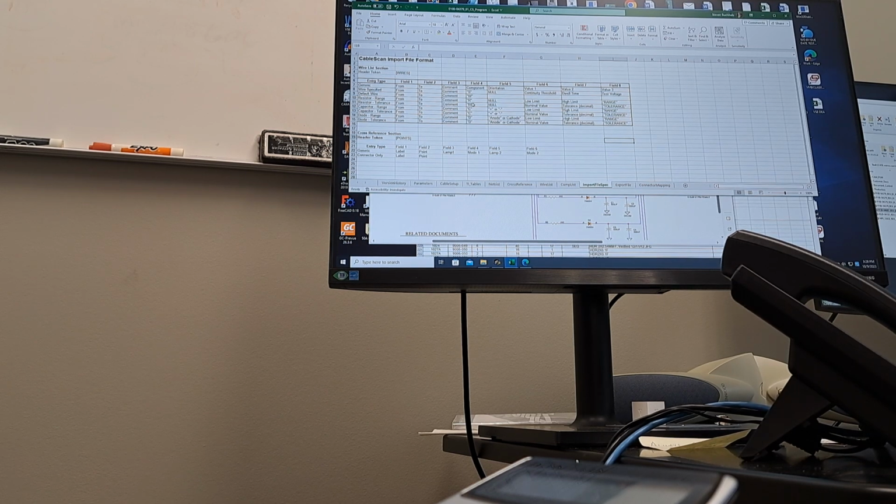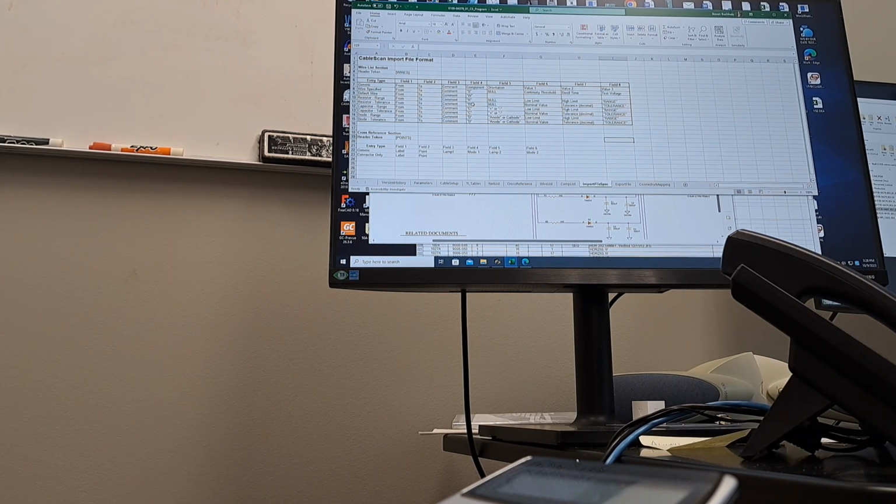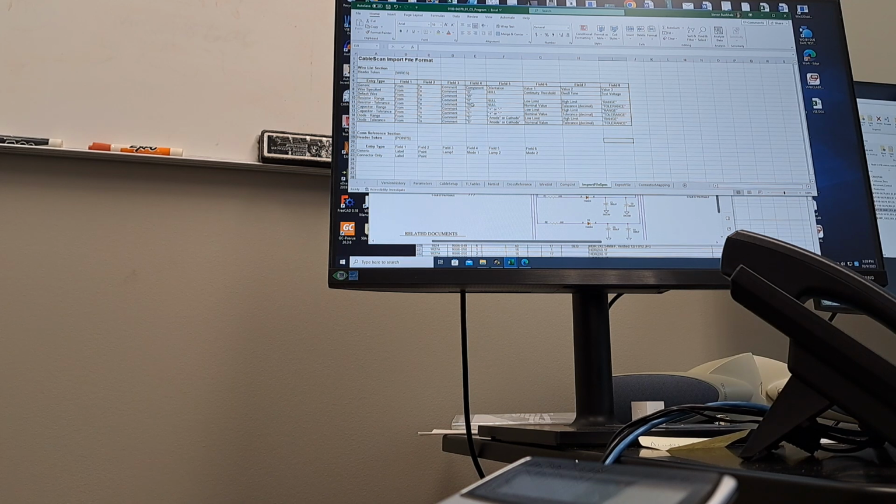If you've got a netlist, you can bring it in, and if you want to, you can filter out all the R's and C's and D's and LEDs and K's and everything. And then run it, and the program finds all of the connections that it can test, and you're done. So it actually helps a lot.